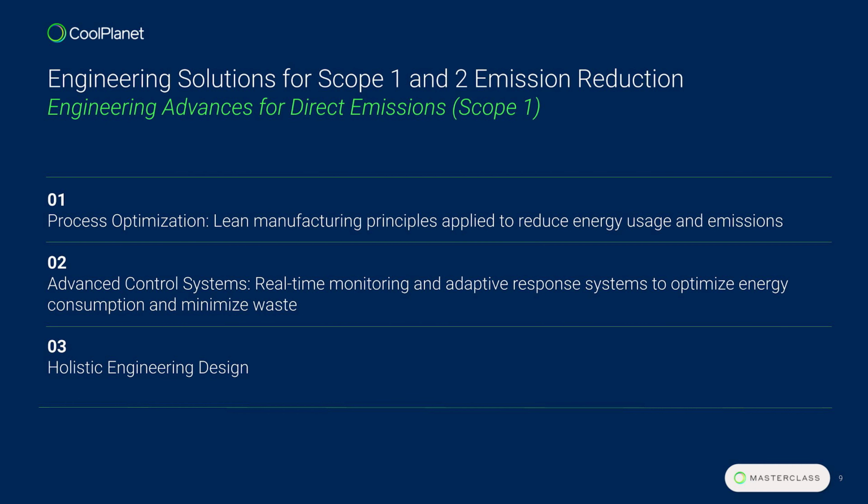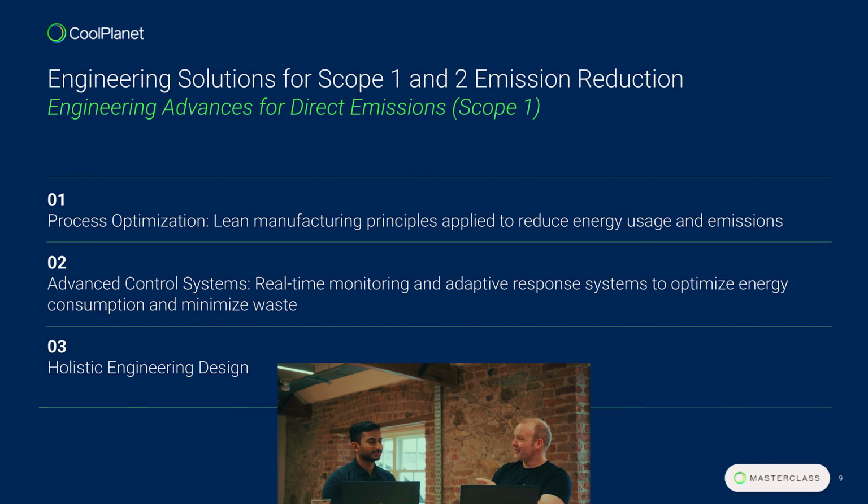Yeah, you could take an example like a boiler, for example. Maybe the spark ratio, the commercial ratio doesn't allow you to go to a direct electrification of heat, but there's an element of heat recovery that could be done. You can implement that heat recovery with a hot water loop. You're obviously reducing the energy or the consumption of gas or whatever it may be for the boiler. But the good news is if you design that hot water loop in the correct manner, that's perfectly the infrastructure you need for a heat pump going forward.